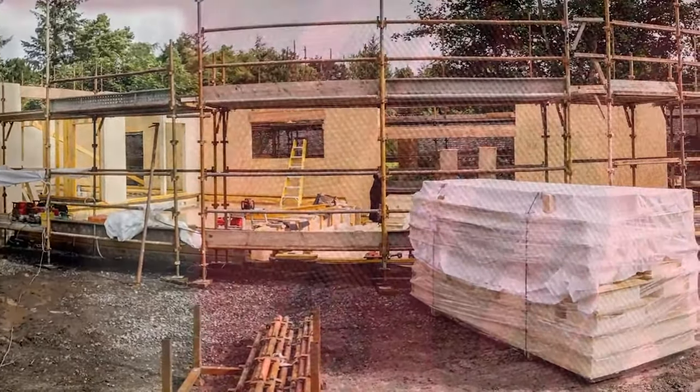That can have a massive effect. Sometimes when you get down to very low U values, taking your air tightness from a level of 7 down to 1 can be the equivalent of putting in an extra 100 millimeters of insulation. So by improving the air tightness, you're looking after the building envelope from a condensation and moisture point of view, but at the same time, you're improving the energy efficiency of the building.